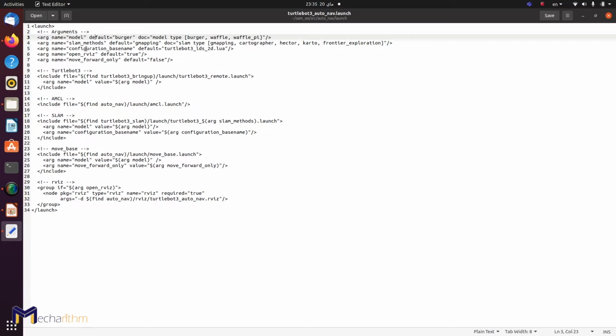We used the gmapping package to generate the map before, but gmapping in itself is a SLAM algorithm. So we use it to generate the pre-saved map, but I can use it online as well to generate some updates of the map as I continue moving. I'll tell you how I launched this file. Actually, this line is stolen as well, but I'll tell you where I got it from, right? So let's just forget the SLAM lines now. I'm gonna get to that.